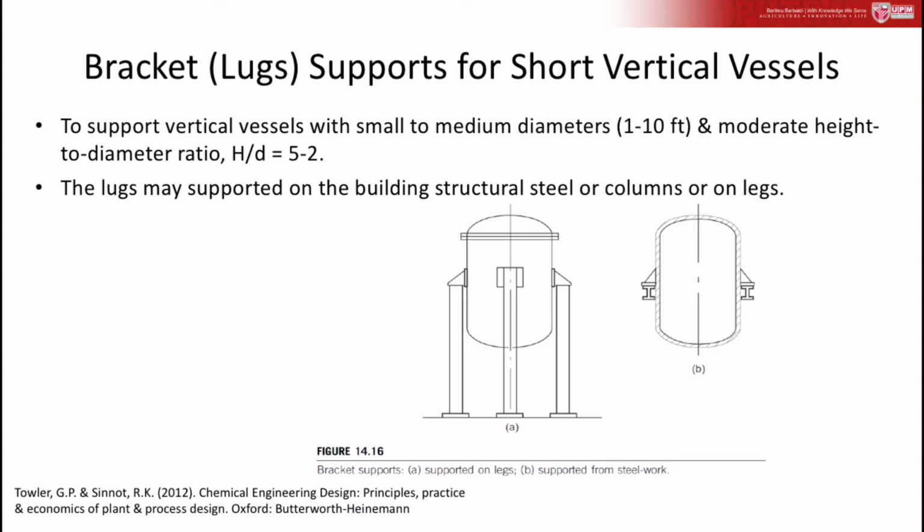skirt supports. It will be very difficult for you to maintain a hygienic area inside the skirt area, because normally in the food industry daily cleaning is mandatory and will use a lot of water. So there is a lot of water accumulation inside the production area, especially on the floor.